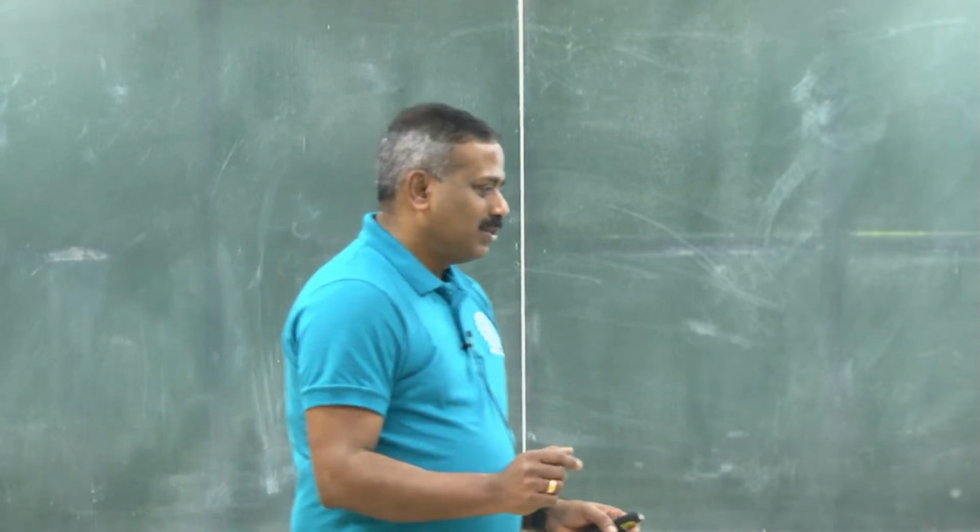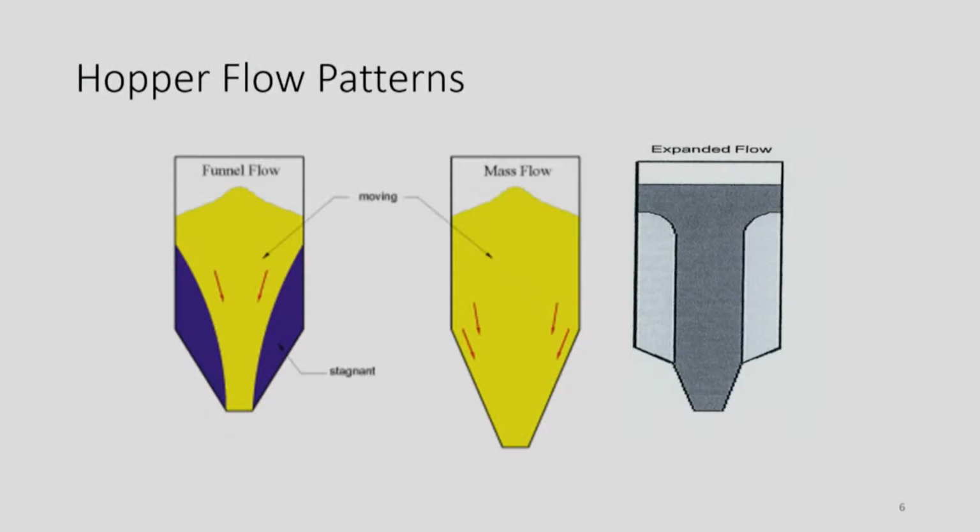For some of you who do not know, before milling wheat is hard. The external part is hard and the starch is softer inside. So what they do is they add water. It could be by steaming, but mostly mixed with water. So the fiber will become a little softer. When it becomes softer, it breaks into larger pieces rather than small pieces. If it's very dry, the fiber will break into very small pieces, then separation will be difficult. So if you add water, they break into larger pieces.